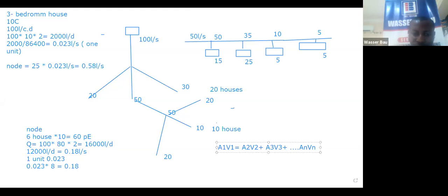So the base demand and the downstream demand give you the total demand at node 6. The next node we're going to compute is node 7. Before we go to node 7, we must get the value for node 11, because node 7 is simply going to be node 6 plus node 11. Before we do node 9, we must get the value for node 10 and node 12.